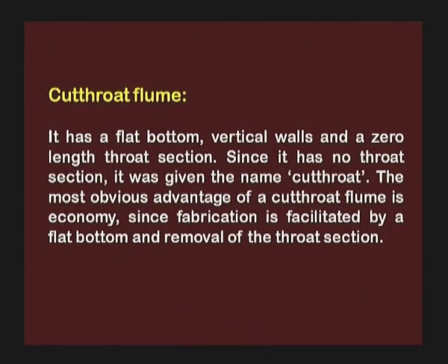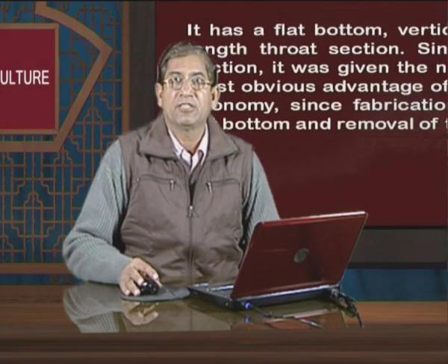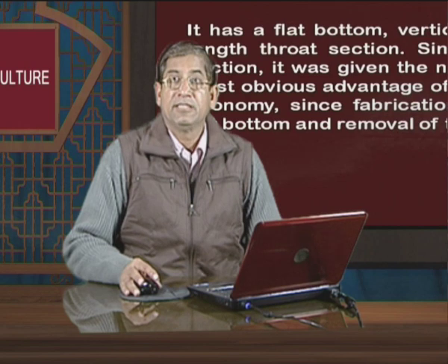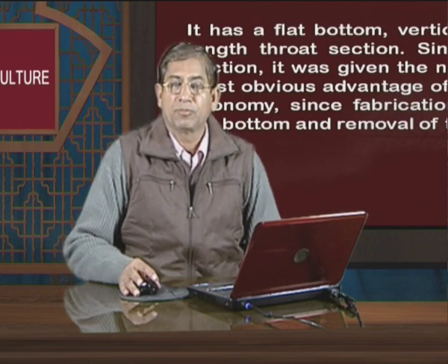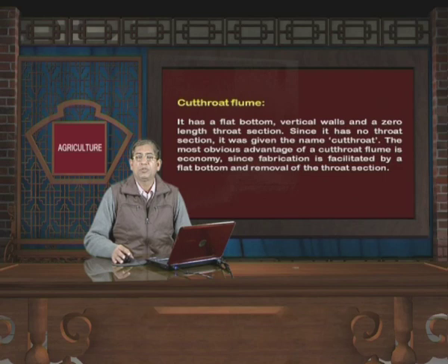Cut throat flume. It has a flat bottom, vertical walls and a zero length throat section. Since it has no throat section, it was given the name cut throat. The most obvious advantage of a cut throat flume is economy, since fabrication is facilitated by a flat bottom and removal of the throat section. An additional advantage is that its fabrication is less complicated in comparison to partial flume, and the cost involved in fabrication of cut throat flume is less in comparison to partial flume. It is easy to measure water